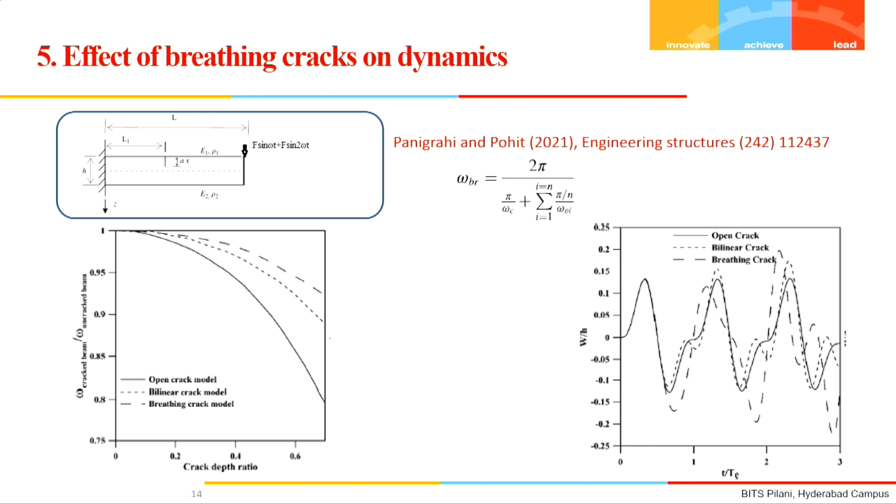So this is what I had to talk about. Even if the crack is not growing, because we assume that the engineering structure will not fail by cracking, somehow if some crack gets developed and we perform online condition monitoring, online vibration testing, so if we have the vibration data from the operating structure, by seeing the shift in the response, we can clearly identify where the crack is.